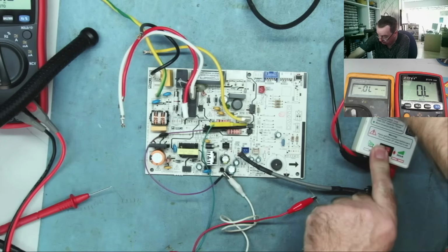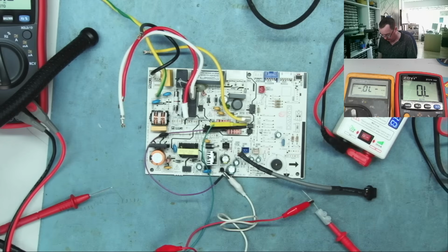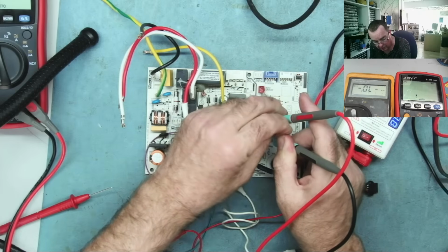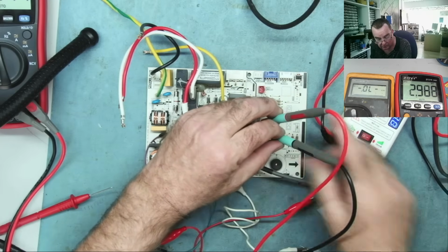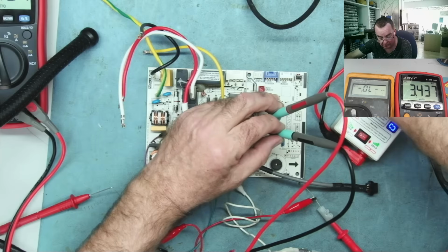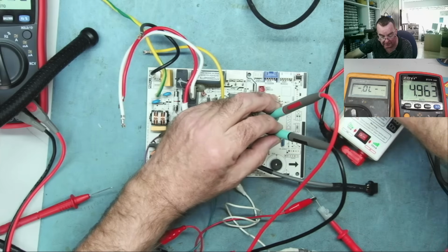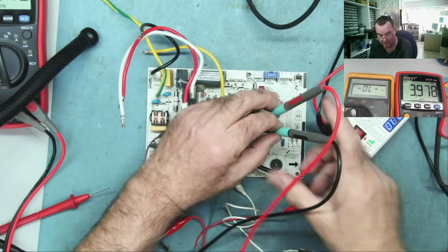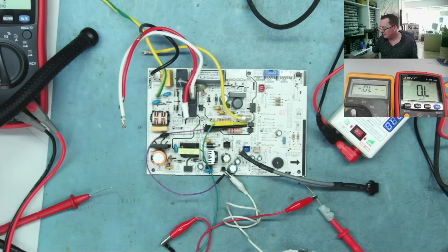Switch it on. 1 volt, okay. And we can measure the output in ohms range. About 3K. Switch the backlight tester off. Look, goes up, yeah. Switch it back on. Comes down. So we can say that that is good.